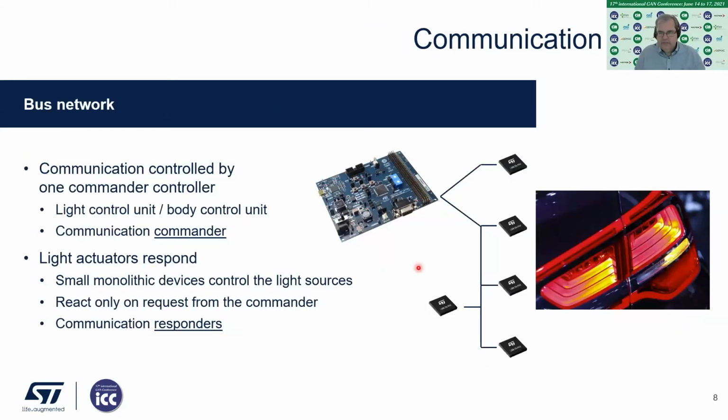So then we thought about what kind of communication concept would be to use here. The first idea that we came up with, yes, it has to be a bus network. Bus networks are very flexible. So we have the domain controller here. The picture here shows our evaluation board. This acts with a microcontroller, so this acts as a domain controller. And these are the LED drivers, the light drivers for the rear light here.